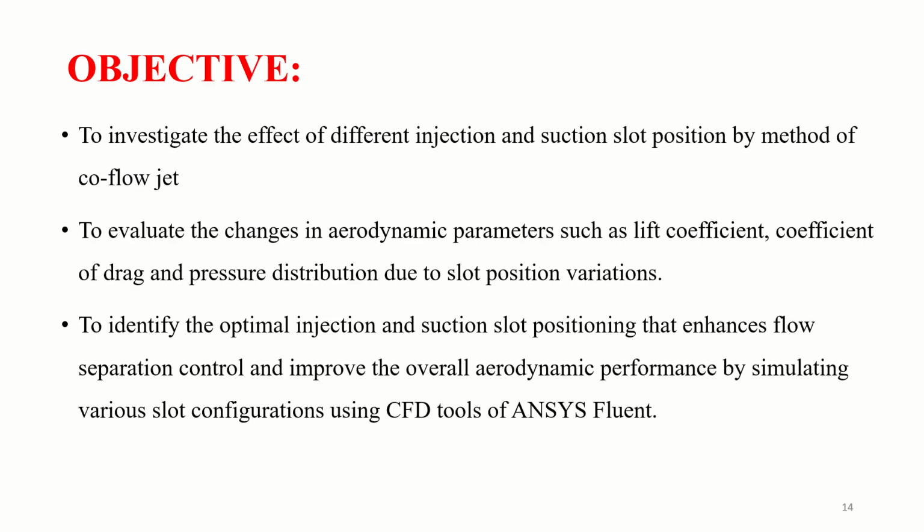So our objective is to investigate the effect of different injection slot positions by this method, to evaluate the changes in aerodynamic performance such as lift coefficient, drag, and pressure distribution, and to identify the optimal injection and suction slot opening and positioning, which enhance flow separation control and improve the overall aerodynamic performance, by simulating various slot configurations using CFD analysis tools.